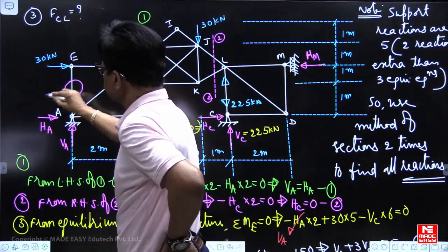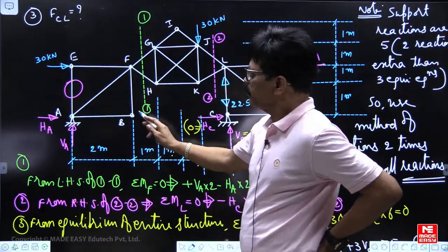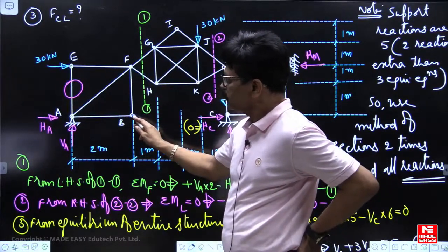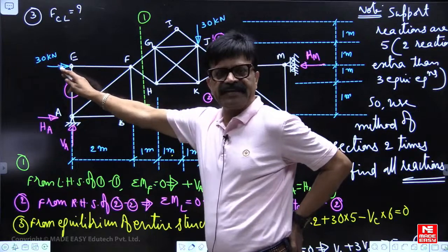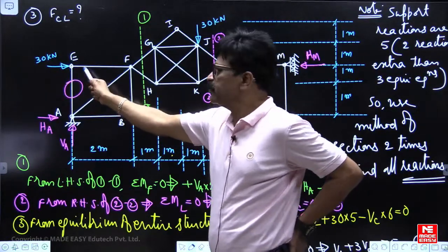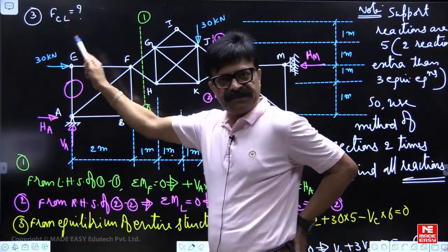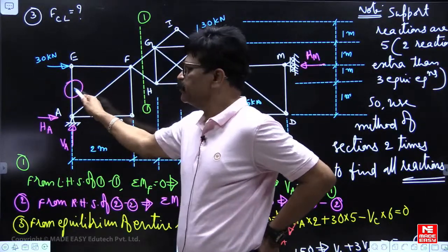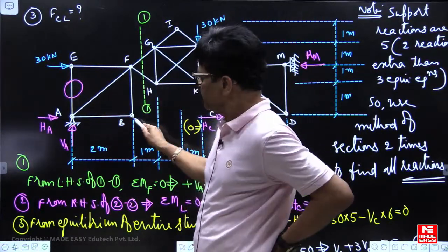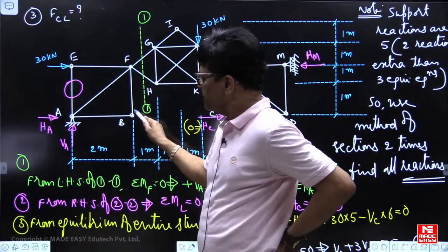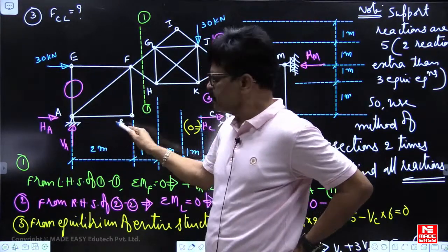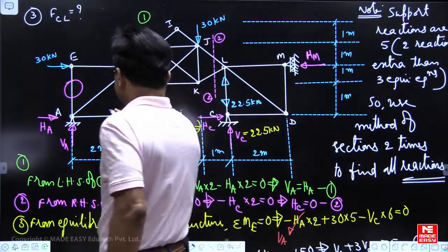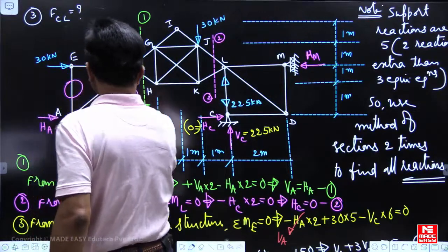Third must be 0. Over. Come here. B. This is one way of detecting whether member force is 0 or not. If 3 members or 3 forces are meeting, 2 forces or members are in line, force in the third member is 0. One thing. Next come here. 2 non-collinear members, no external load, so forces in both members are 0.